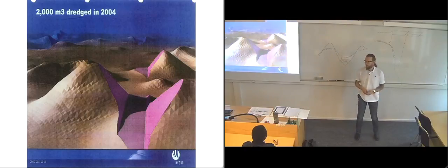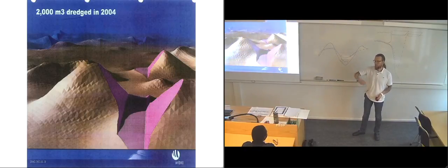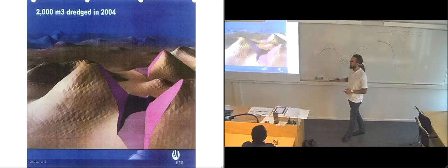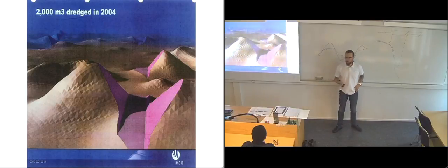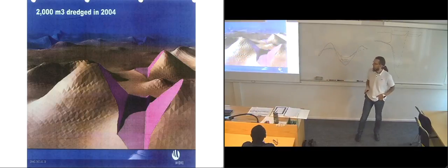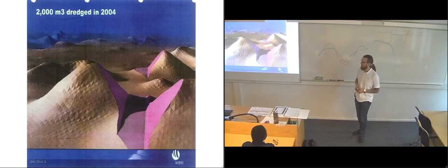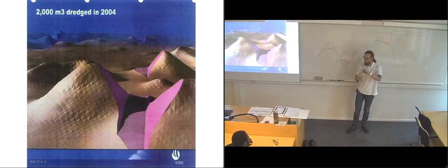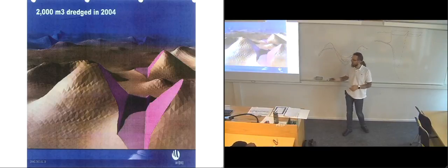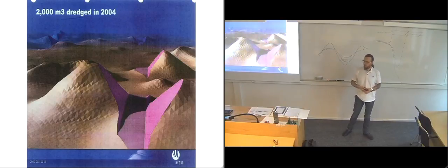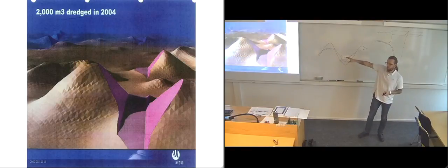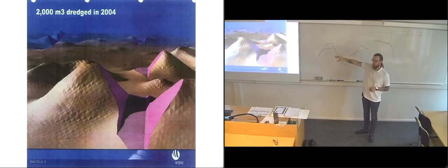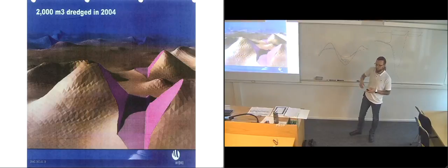An excavator on land will use its shovel and it will just dig and dig, while often on the seafloor you will use water jets. So basically what you're doing is you're creating suction with a water jet in a pipe, and then a different part of the pipe will be angled down into the sediments, and the suction created by the water jet through the rest of the pipe will start sucking the sediment through the pipe also.